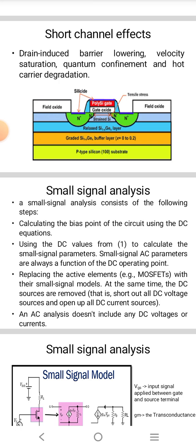These amplifiers initially have to be biased to a particular operating point where we get maximum amplification. This biasing point defines the drain current and the VDS voltage at a particular VGS voltage. So these 3 parameters are defined by the operating point.